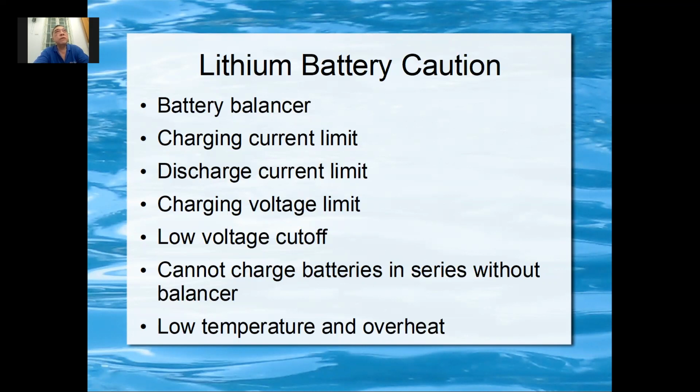All these problems. And when you are charging, make sure you have a voltage limit. You charge until full, then it cuts off. If you don't cut off, the electronics inside the battery must cut off for you. If the electronics inside the battery didn't cut off, or you don't have any electronics to do the cut off, you must make sure the charging voltage is limited to, let's say, if it's a 12-volt battery, up to 14.4 volt, then it should stop.